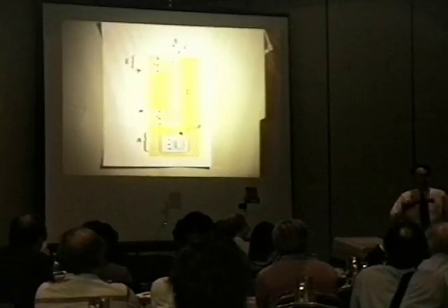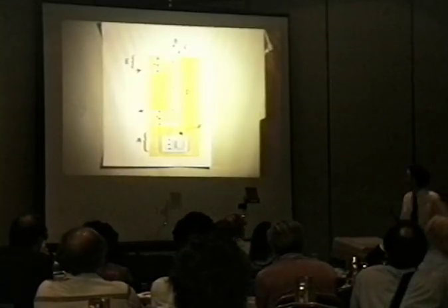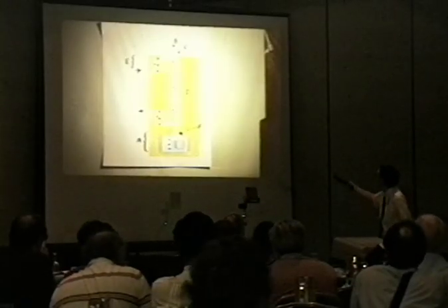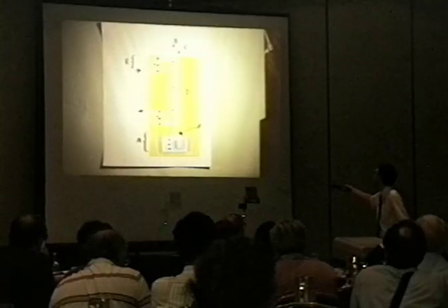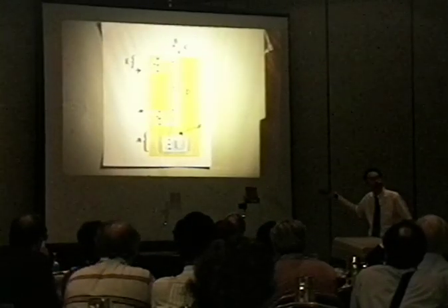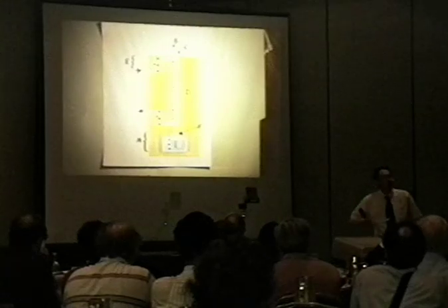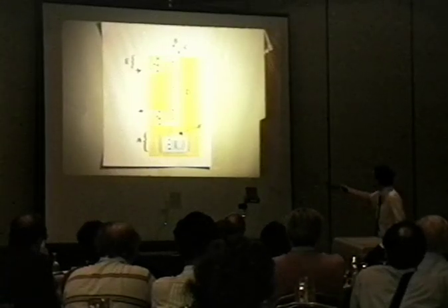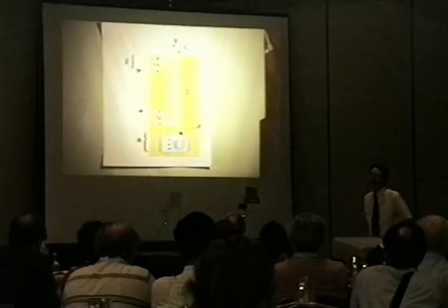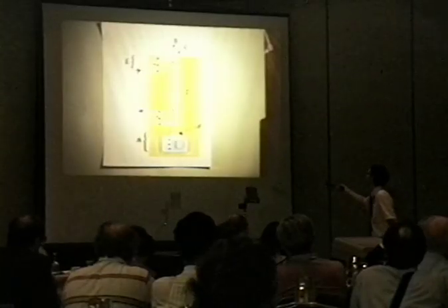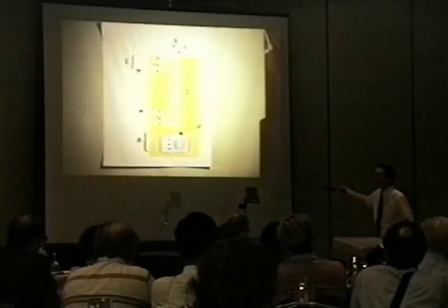Anybody trying this, there's two subtle things you need to be aware of that I need to point out. Number one, this does not come down on axis. It's off axis because you're returning cold liquids that are devoid of your electrolyte. It's distilled water. So if you come right down on your cathode, it messes it up. It cools it off. It stops your electron. That took me a long time to figure out. But anyway, you want to return that off axis.